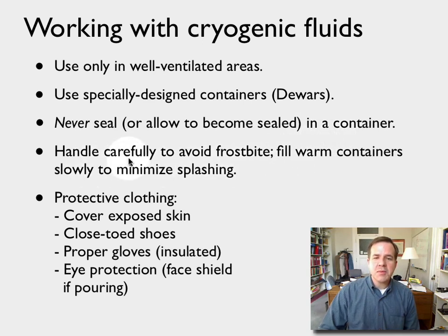We always want to handle cryogenic fluids carefully to avoid frostbite. We don't want to have cryogenic fluid splash on our persons. One of the big risks is if you take a cryogenic fluid and then you fill a warm container. Of course, as you do that, there's going to be a lot of splashing until the warm container cools down to something close to the temperature of the cryogenic fluid. So you always want to fill containers slowly to minimize that kind of splashing.